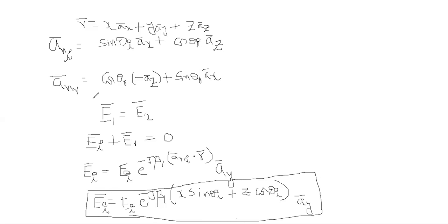Okay. And in a similar way, you can find the magnetic field also. What is the magnetic field? HI bar is equal to, the ratio between the magnetic field and the electric field is the intrinsic impedance. Now, you can apply a cross product, ANI cross E1 bar, whole divided by eta 1. Why am I taking eta 1? Because it is on the left hand side, where the parameters are N1, eta 1, epsilon 1, mu 1, sigma 1 like this. HI bar is equal to ANI bar cross EI bar by eta 1. The eta 1 is the ratio between EI and HI only.